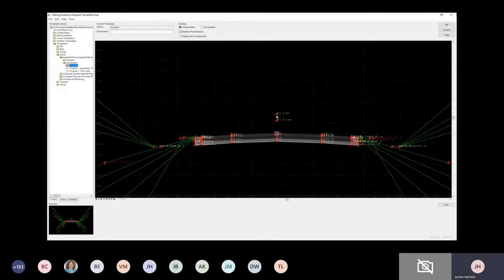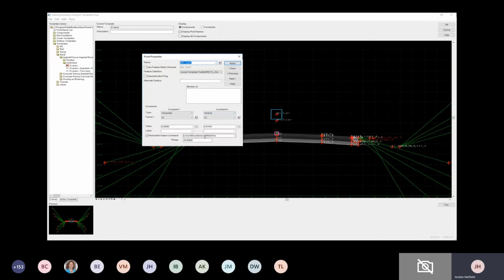I'm going to select a null point on the top, which we like to refer to as a kill, to kill the shoulder and switch off the end conditions. It's sort of like an end condition override, except that the shoulder is not in the end condition, so it's a little bit more helpful in this case. Notice it's targeting match line.